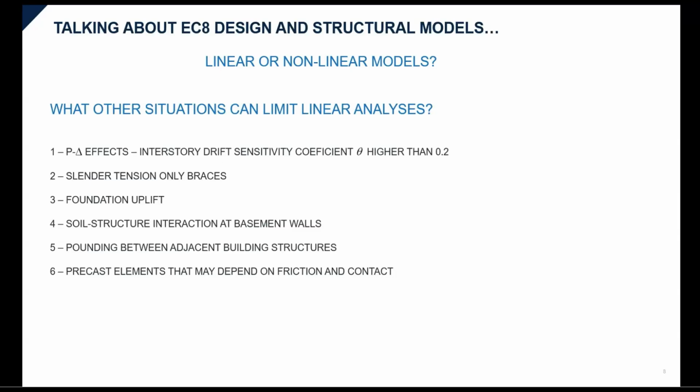Well, if we have considerable p-delta effects in the structure, or theta values greater than 0.2. Slender bracings whose behavior cannot be characterized by linear analysis. If we have foundation uplift, soil structure interaction in basement walls, pounding between adjacent buildings, which would need to be evaluated in nonlinear time history analysis with contact. And finally, precast components that rely on friction and contact behavior.